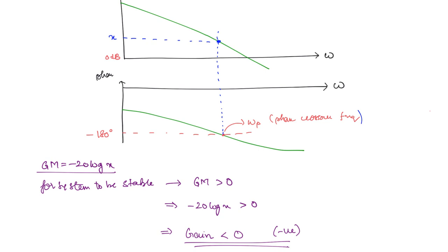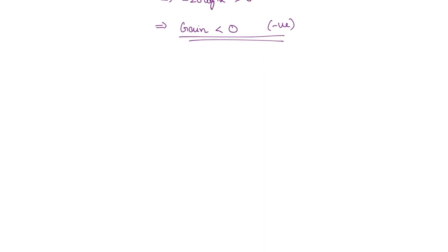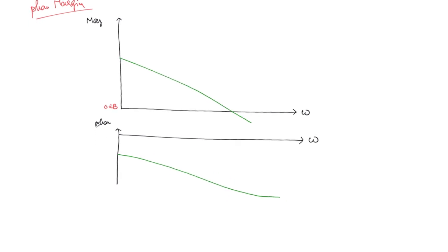Similarly, you can find out the phase margin, right? This is also the same procedure. So we will take the same function and we will see how to do this. Okay, so this was the function, and once again we will take minus 180 to be somewhere here. Now what do we need for phase margin? We will need the gain crossover frequency. That means where the magnitude is crossing 0 dB. So this is going to be the gain crossover frequency omega g.